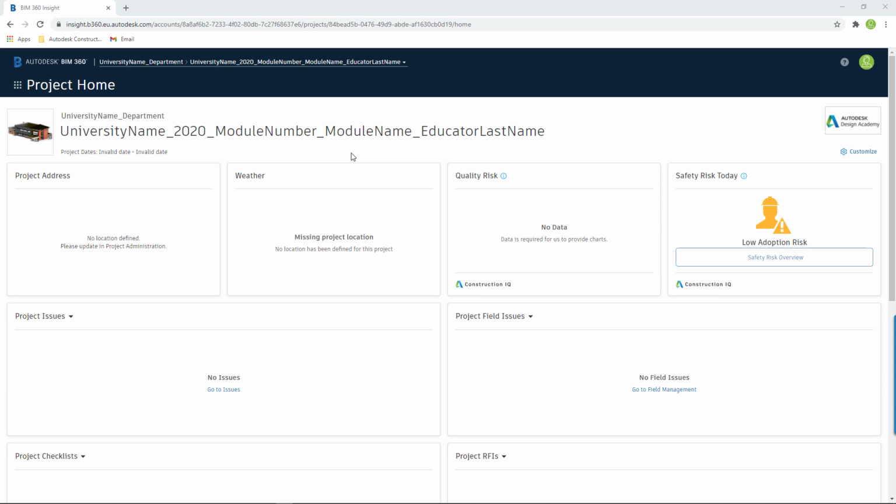In this lesson, we're going to set up BIM 360 to work within the team environment. Prior to setting up design collaboration, we're going to create a folder structure within document management which will replicate our team and group areas. Selecting the module selector, we can choose document management.